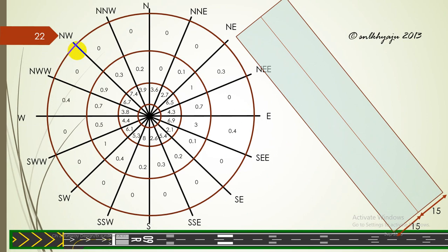In this case, this template is laid over this direction map, and the total percentage covered by this template is summed, and the total sum of the individual number of trials is taken, and the maximum value of the percentage is taken as the best runway orientation.